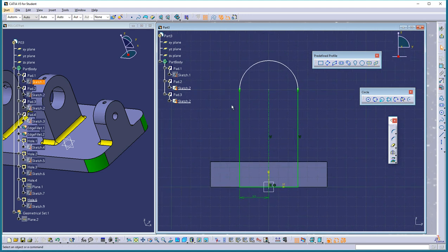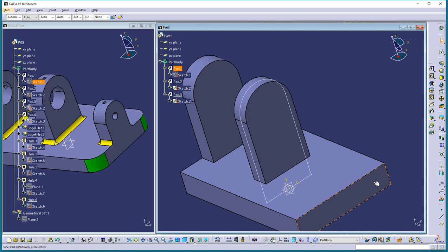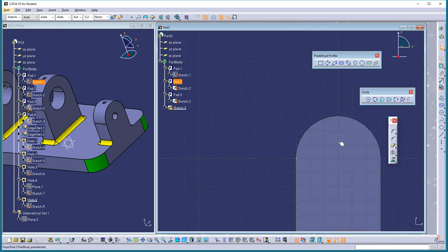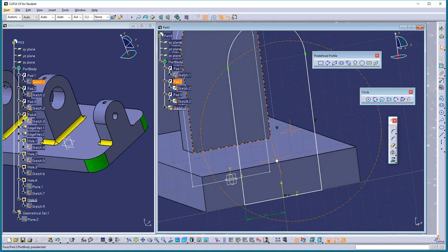And now I'm going to select everything by pressing and dragging, and then Control C to copy, get out of Sketcher, and now I'm going to sketch on this sketch plane. So I'm going to pre-select the sketch plane, select Sketcher, and now I'm going to do a Control V, which is paste. And I pasted everything from the other sketch plane into this one.